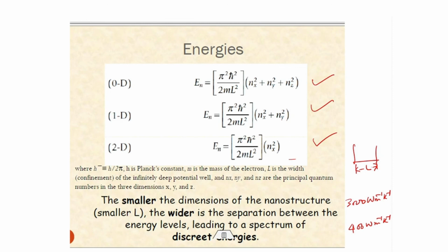So this is what I discussed in the lecture, let me just summarize. I talked about thermal transport. Thermal transport happens because of the electrons as well as the phonons in the materials. Electrons, we know, can easily absorb energy and take the energy away. Phonons are something new. Phonons are lattice vibrations. They are created because of the motion of the atoms from their mean positions, leading to push and pull of the atoms and creating a traveling wave in the material. And these waves can take the energy from one part of the crystal to another part of the crystal.